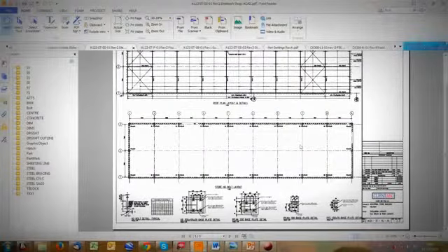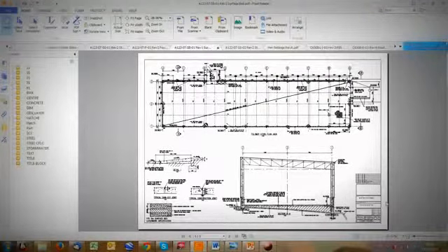Often mistakes are made, or often drawings are not done well, and it takes experience to know what contractors need, and also what can be done wrongly, what can be done simply, and also how you're going to build this thing. How do you produce this in such a way that the contractor or whoever it is can actually build it? And also you must remember that these drawings don't just go to the contractor. They might go to the client, to the council for approval, and all those things. So you need whatever information is required for the different parties to use it.